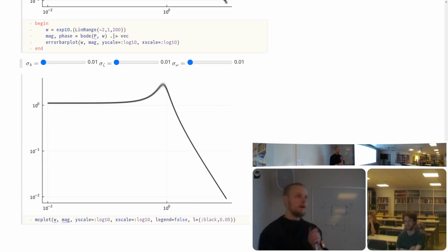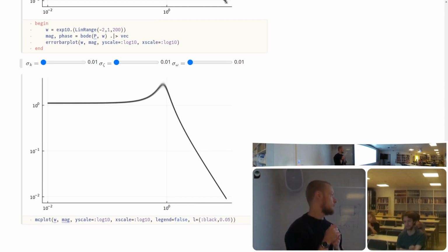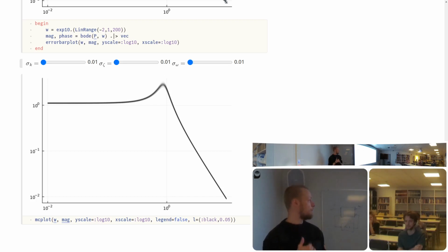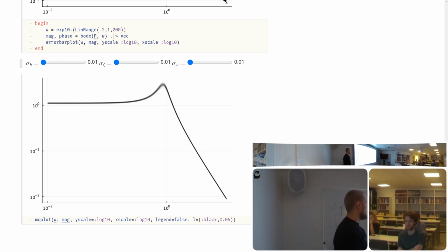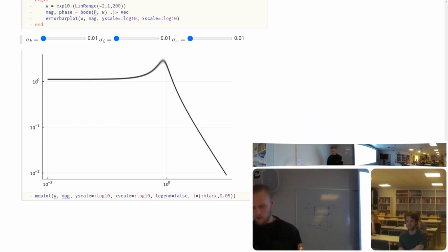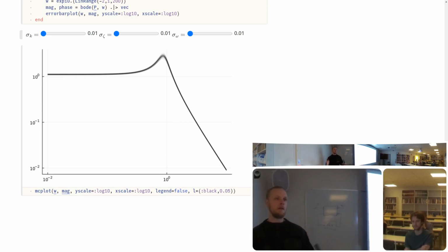All right, so you can combine the control system package with other packages from the Julia ecosystem. So Monte Carlo measurements is one such package, but you can put intervals in there. You can differentiate through things using forward, for instance. So when you do that, the transfer functions will have coefficients of dual numbers. And that's perfectly fine. You can differentiate through, say I compute a Bode curve, and I would maybe compute the H2 norm by summing over the frequency response, and then I would have that in my cost function. That is fine. You can do that. So you can tune PID parameters with constraints on the H2 norm quite easily.